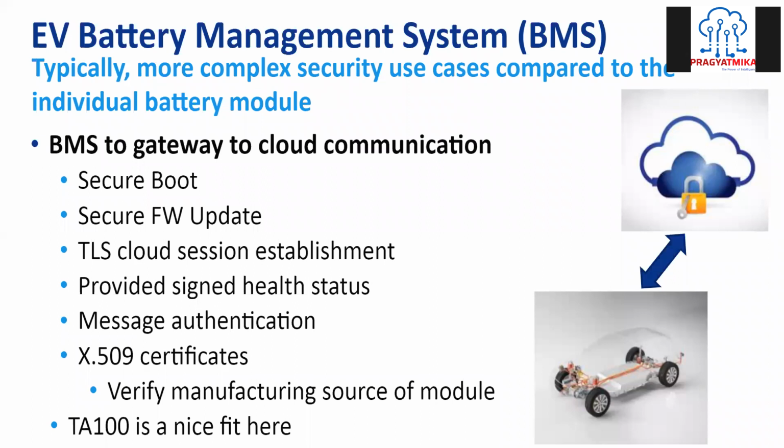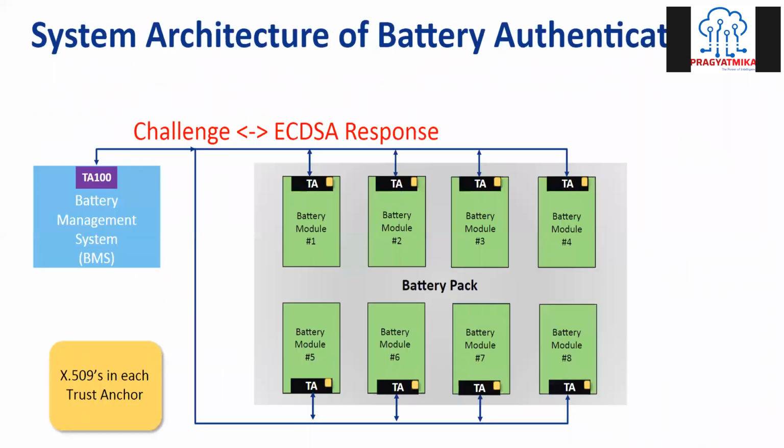So there is one complete connector-type solution being brought out. This is the TA100 connector, which has inbuilt security hardware and certificates that can be signed on those hardwares, and those can later be connected with your cloud. So the TA100 could be integrated with your battery management system, and on each battery module, this TA100 will be implemented, and further it can be communicating with the battery management system.